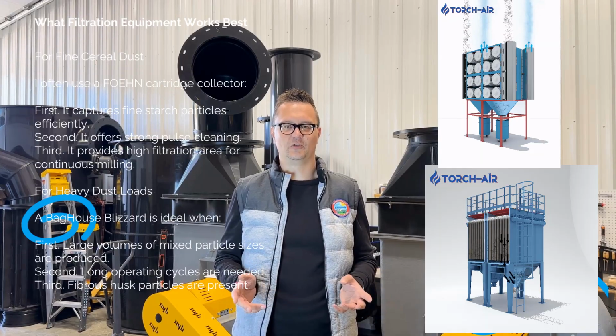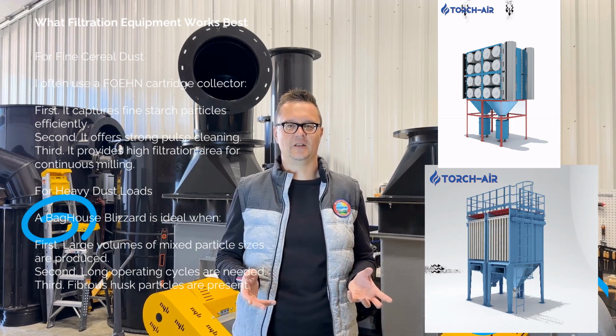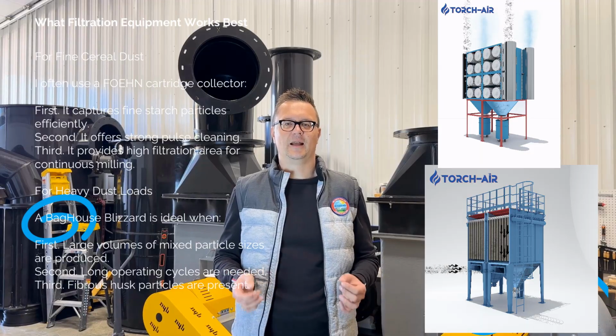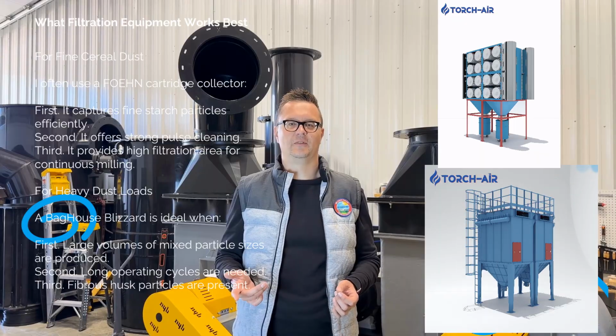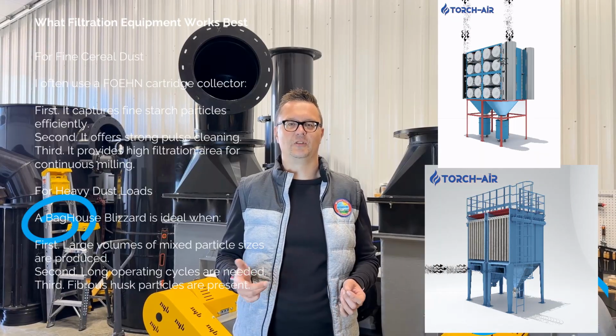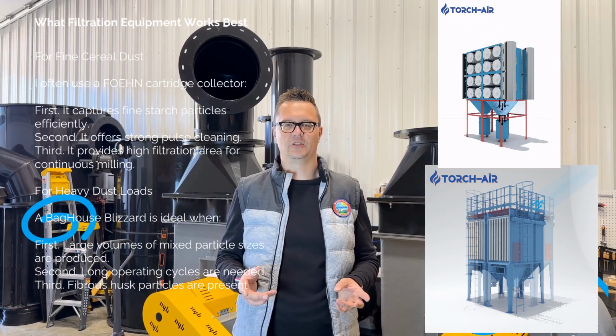Explosion protection. Agricultural dust always requires: first, explosion venting. Second, duct isolation valves. Third, anti-static filter media. Fourth, grounding and bonding across all equipment. Fifth, optional spark detection for mills and grinders. There is no such thing as a safe grain mill without explosion protection.